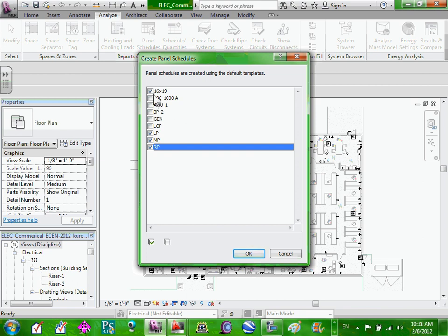I'm actually going to unplug that one here. The only thing I need to do is LP, MP, and RP. You can even run a schedule for the fire alarm panel. That's 1619, I believe it was the fire alarm panel. The only 3 schedules I'm asking you to do are lighting, receptacle, and mechanical. Can I have thumbs up that we got it, Chad? You can run them once. If you try to run them again, you're not going to find them here because they're already under schedules and they will already be updated. Every time you update, it will auto update.